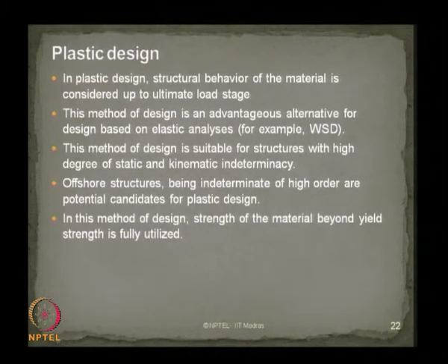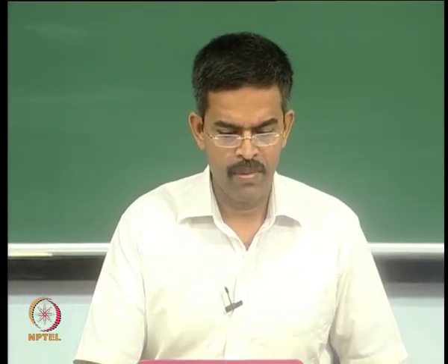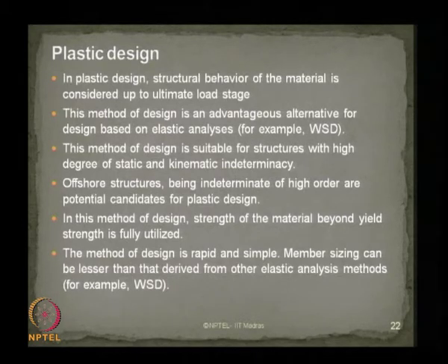In this method of design, the strength of the material is not stretched beyond the yield strength of the material. There is always a wrong notion among designers that in plastic design the stress value will exceed Fy. The stress value never exceeds Fy. The method of design is rapid and simple. Member sizings can always be smaller than those derived from conventional elastic analysis like working stress design. So, plastic design leads to an economical sizing of the member, as the yield stress is never exceeded and is used to its optimum value in the design.